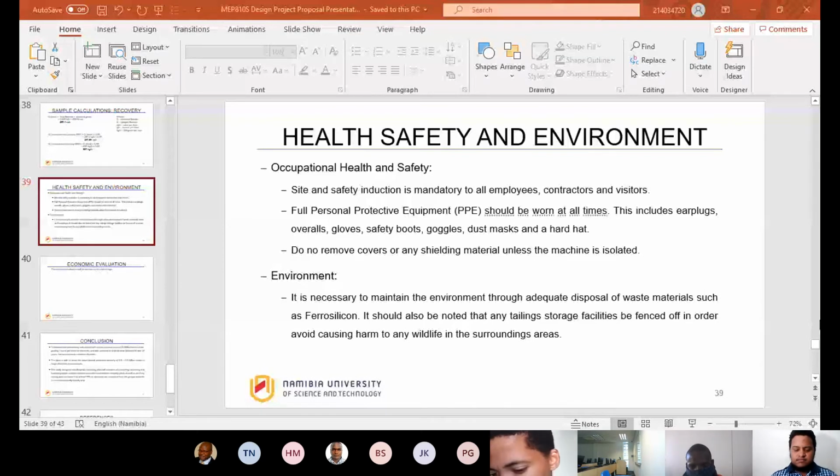So these types of spillages, especially as we will be using reagents in this dewatering section, the thickening, should carefully be looked at in terms of daily analysis to see how much flock is being sent to the tailings, and how one can reduce such discharge to the tailings.